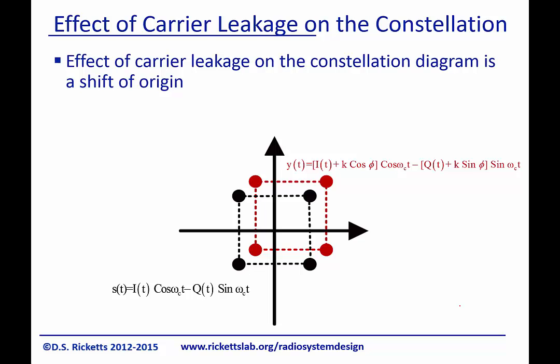You might be thinking, well, it's a DC offset, that's not a problem. However, if you imagine that you're a receiver, and what the receiver does is it says anything in this box is 1, 0. And so if your received symbol, if you will, marches out of that box, it's no longer going to receive the correct signal it should.